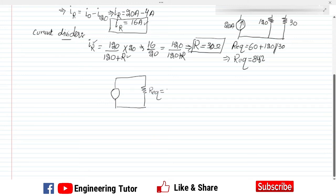The value of R equivalent is 84 ohm, and the value of this current source was 20 amps. So what will be the voltage here? The voltage V84 will be equal to the 20, which is the series current coming here, multiplied by the 84. It will have some value. So after calculating this value, let's suppose it is some value.